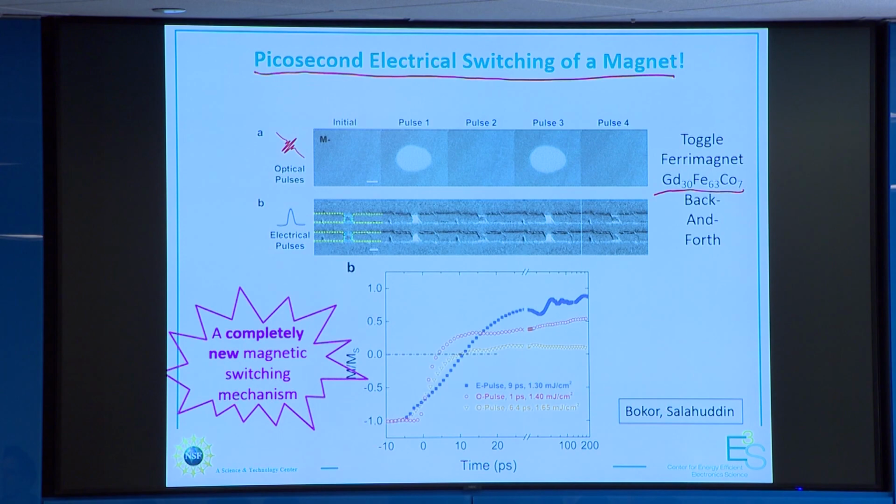So the slide that I'm missing is how you're going to use this. And the way you're going to use this is you switch the magnet. The magnet switches a magnetoresistor. So you have a magnetoresistor in every hard disk as a magnetic field sensor. The magnetoresistor, you apply a bias voltage so you get current. And that current drives the next spin orbit torque switch. And so you have essentially an electrical device, current in, current out. And inside the black box, inside the transistor, is a magnetoresistor and one of these spin orbit torque switches.